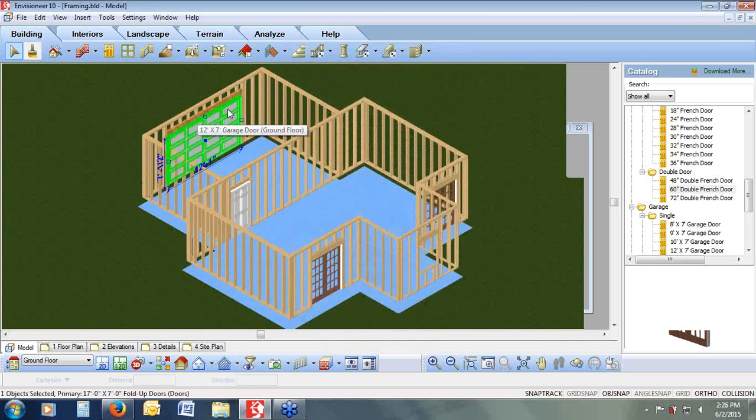It's automatically looking at those span tables and saying, oh, well, we've got a 5-foot opening here. I've got up to 10 feet. I'm going to use my 2x10, so I'm going to use that one. But then, hey, this is over that span. I'm going to use the next product up.